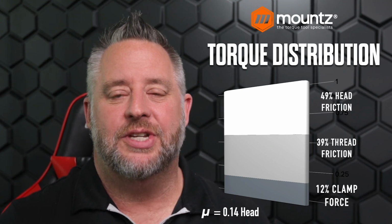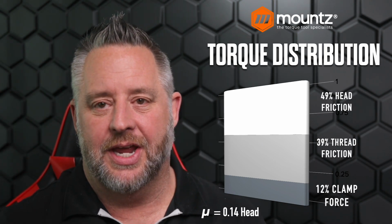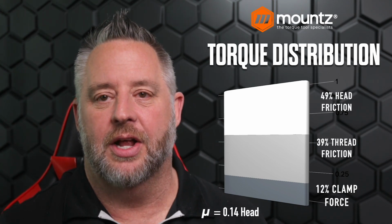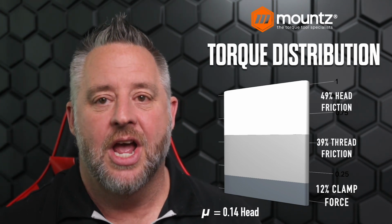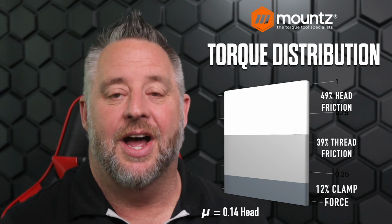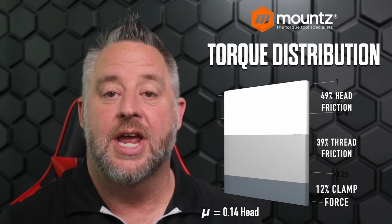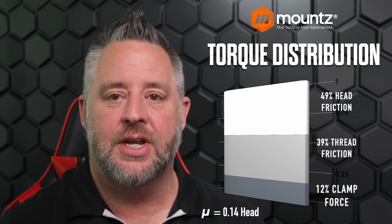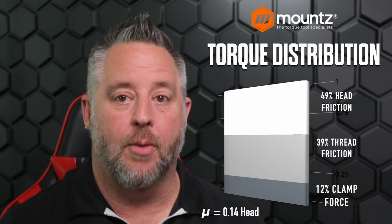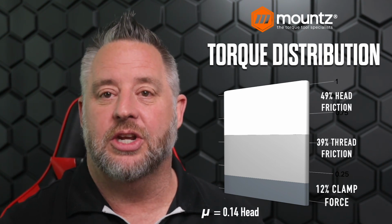If we were to decrease our head friction by just 10%, what kind of influence would that have? And you might say, well, how can I eliminate 10% of my head friction? Well, this can be done very, very easily. Let's say the operator grabs a different washer that might need to be used. That particular washer may have a different diameter to it. It may be a different size. It may have a different coating to it. Or the operator may not use the washer at all and forget to use that.